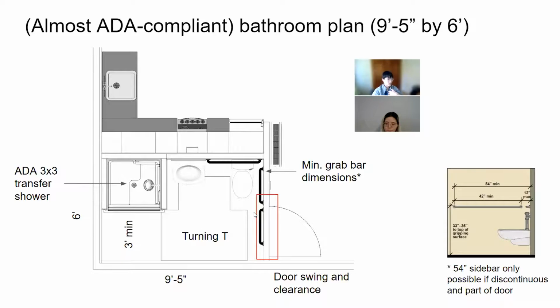Now, from a user perspective, the average user might look at this and say, this is totally sufficient from a use case when it comes to having grab bars where I need them to be able to navigate on and off the toilet. From an ADA compliance perspective, we have no idea yet whether this will pass the sniff test. And that's in part because we didn't have to get these designs permitted for ADA. So we just presented designs without saying anything about ADA. And I don't know if there would ever be a situation in which we need officially for this project to be ADA. So right now, what I'm describing this is it's almost ADA, but maybe effectively and practically for our end users, who are the ones we ultimately care about, this might be sufficiently wheelchair accessible.